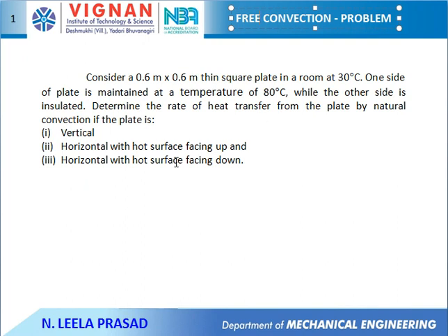Consider this free convection problem. Here the fluid properties, that means air properties, must be taken at film temperature. Here the film temperature is T wall temperature or T surface temperature plus bulk fluid temperature divided by 2. So the film temperature here is 55 degrees Celsius.